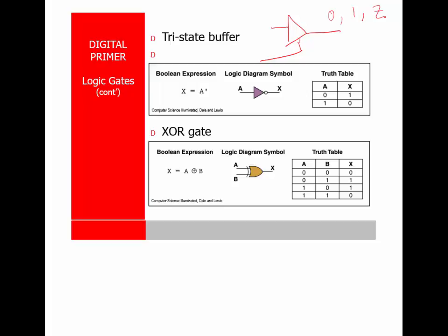I've worked on circuits where these timing glitches created huge problems. Huge problems. Because you designed them with a certain technology, probably a 74XX family, and then you change the design to a 74HC family, which is a faster family, so it can react quicker to changes.